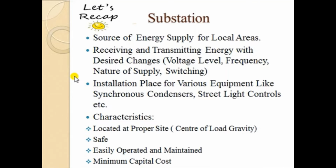What are the characteristics? You have to choose a proper site for a substation, and the most economic site is at the center of load gravity. This is not a geographical center. You have to put a substation in such a manner that all the loads are at an equal distance from it. So it is called the center of load gravity. Substation operation has to be safe, should be easily operated and maintained, and must have a minimum capital cost.